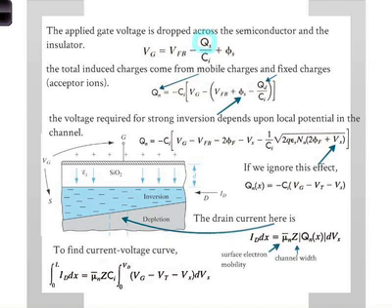What is at the interface? There's a difference. So that's oxide. What is this material? It's silicon. At the interface, what do you have? You have imperfections between oxide and silicon. You have a crystal lattice difference. Which means, of course, what does imperfections mean? That the carriers will scatter off it. Remember we talked about mobility, and when you increase doping, you get lower mobility and things like that. Exact same thing happens here. As the electrons get closer to the interface, they scatter more because they see more of those dangling bonds and charges that are trapped there and so on and so forth.